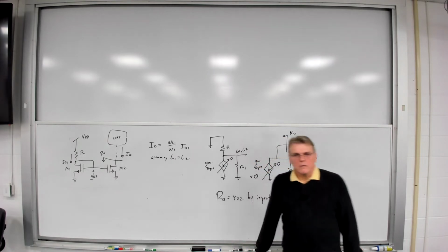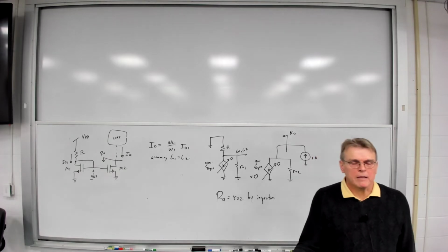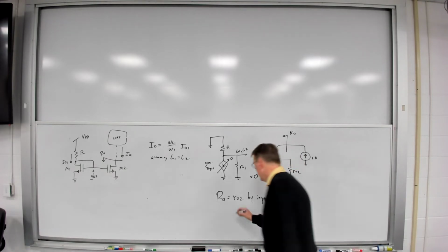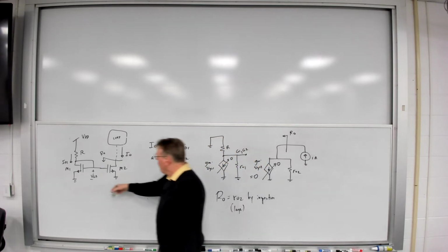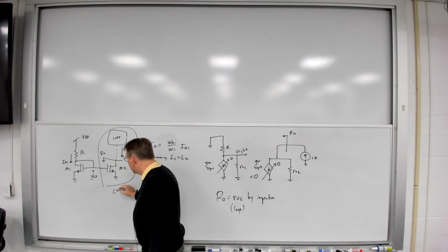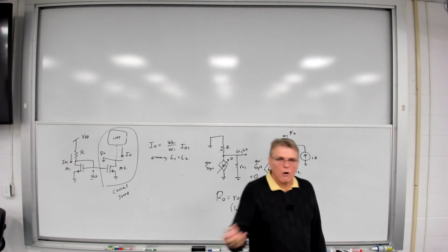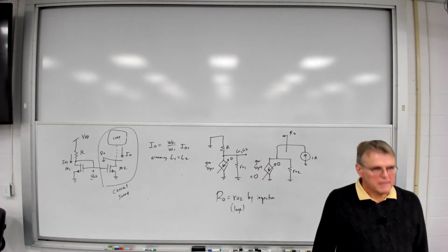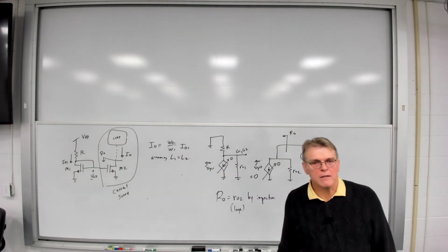What is RO2? Well, it's a large resistance, right? Typically in the tens or hundreds of kiloohms or megaohms. Now keep in mind, we want this transistor to behave like a current source. Does the fact that R sub 0 is large fit in with that? Yes, it does, right? Current sources have infinite resistance. Well, that's not infinite, but it's large.